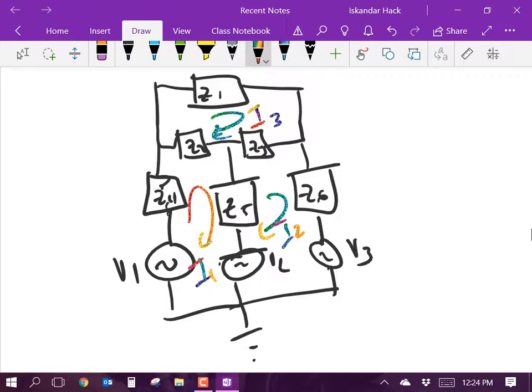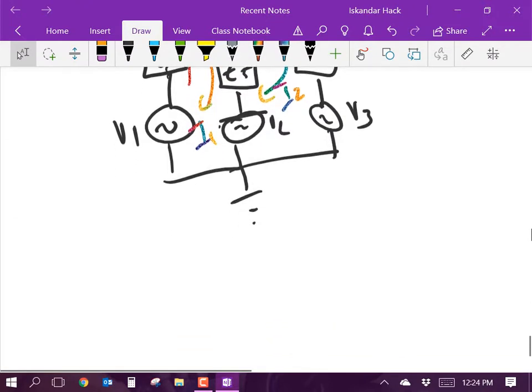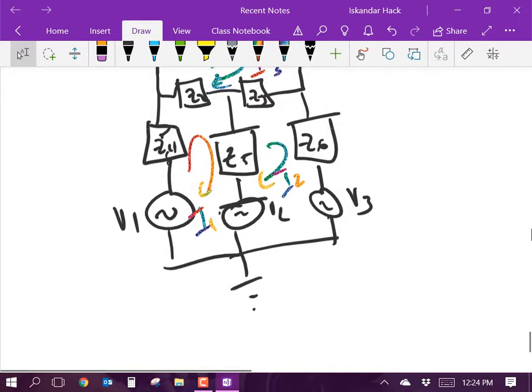So I've got 6 impedances, and I can write the equations. I'm going to write one or two of the equations, and then point out that I don't necessarily write the equations. But first off, you have to show a polarity for each of the voltages, because those make a difference. Because as you write the equations, you use the polarity that you enter.